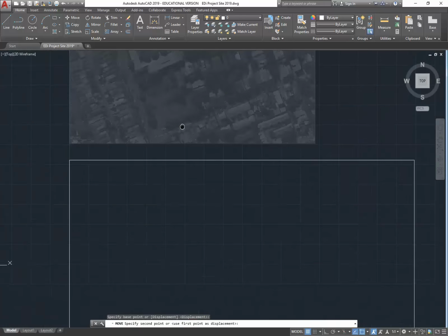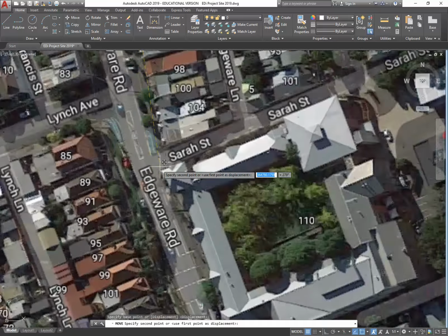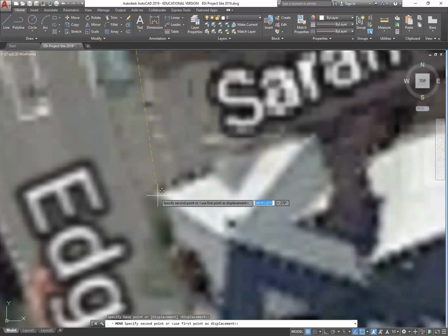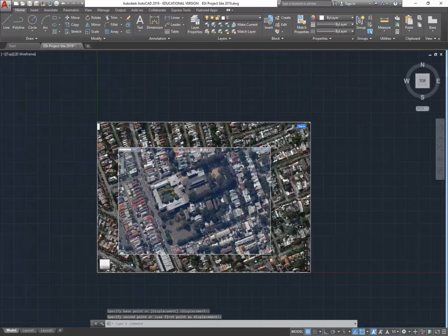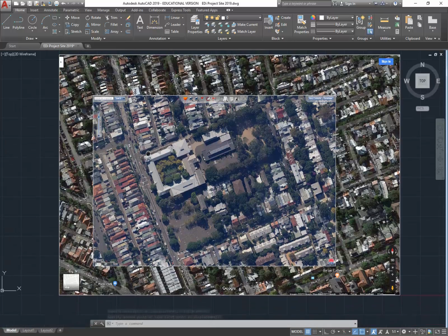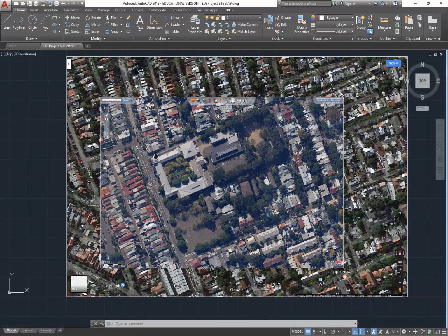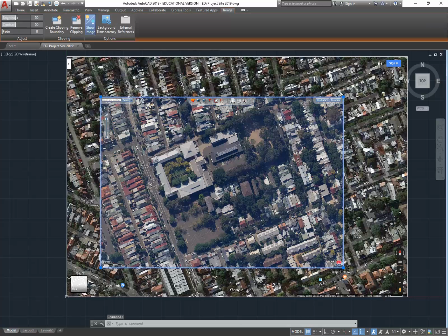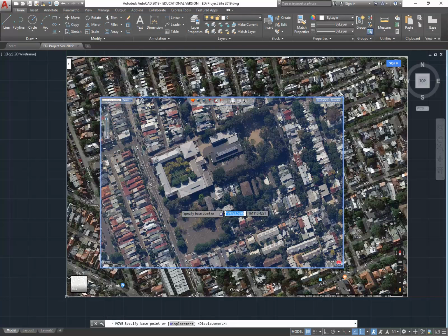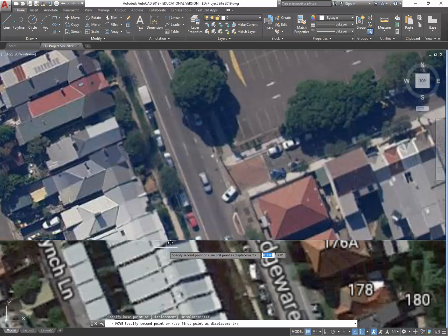And then go down and click on the same point on our original satellite image. That's a bit clearer. So it's fine to overlay them, and if you've scaled them correctly, then that's a good way of checking, because they should line up. So you can see there, well, it's the same size, maybe it's slightly off though, because these houses are exactly in line, so I'll just again move that across slightly, just to line it up as best I can.